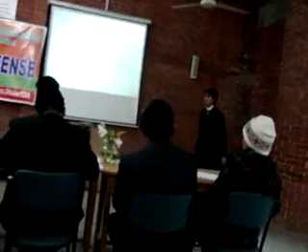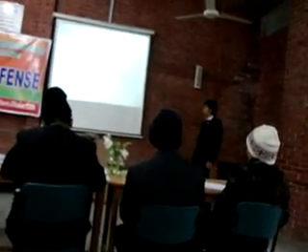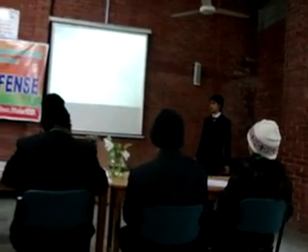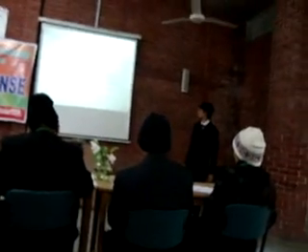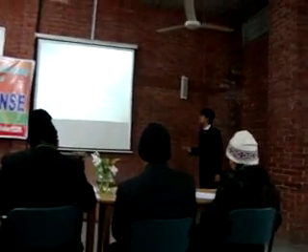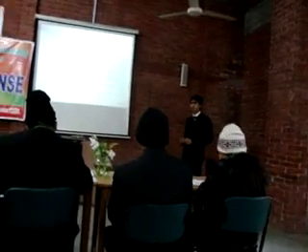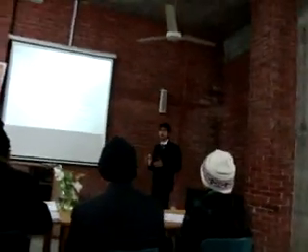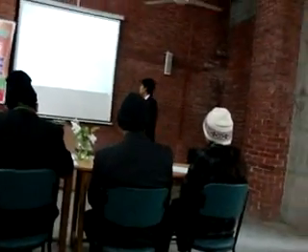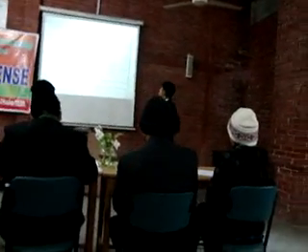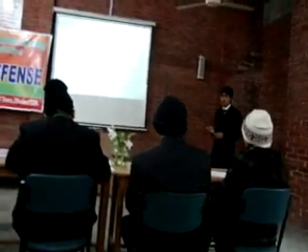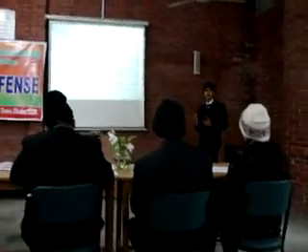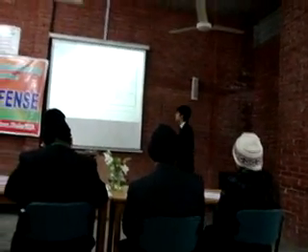The input module is interfaced directly with input devices. It receives signals from the input devices and sends them to the processor. The input module sits in the middle between the processor and the real input devices. This is the output module. The output module is the interface with output devices, and it is also in the middle between the processor and the output devices.